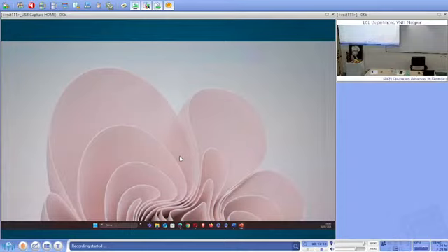Sir, is it only for the vegetation, or can it be detected for rock pits under sea level, for rocks, rough rock surfaces? Yes, but not under sea level in general. So is it only for the vegetation? No, it's not only for vegetation. It's for the shape of vegetation. The basic point is that this type of reflection, rotating the polarization, is caused by complex, particularly complex shapes. And the epitome of a particularly complex shape is generally vegetation.